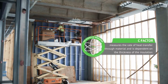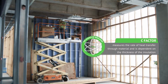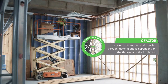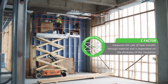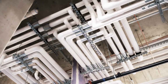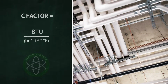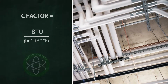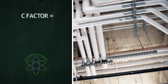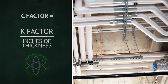C factor is the thermal conductance factor. Much like the K factor, it measures the rate of heat transfer through material. The C factor is dependent upon the thickness of the insulation. Thicker insulation material will have a lower C factor and will thus be a better material for insulation. To calculate the C factor, you divide the BTUs by the hour per square foot per degree of Fahrenheit temperature difference. The C factor can also be calculated if you know the K factor. Then it can be determined by dividing the K factor by the inches of thickness.